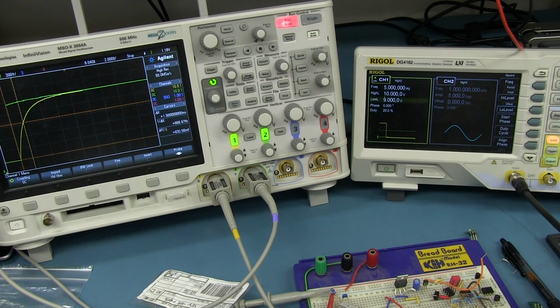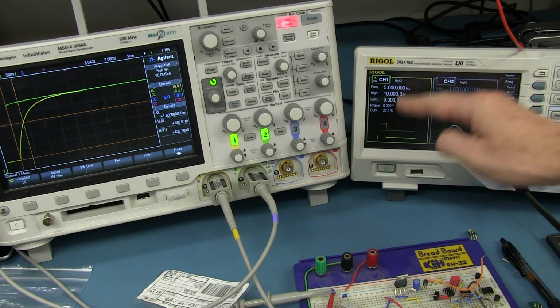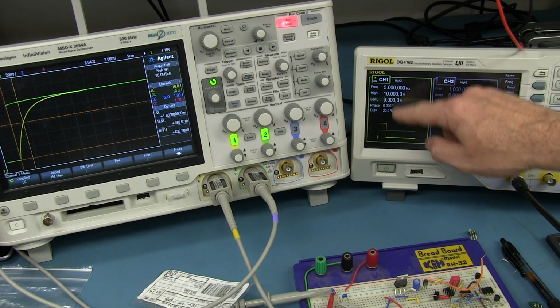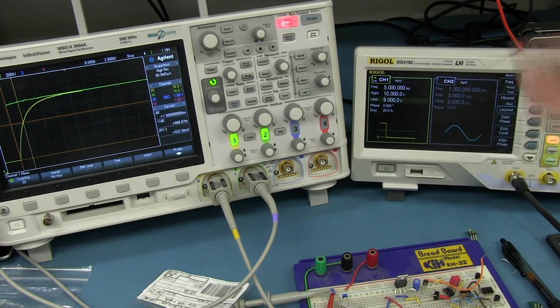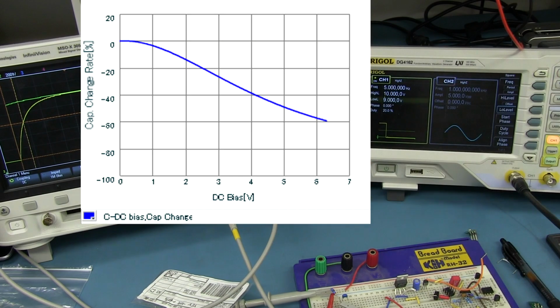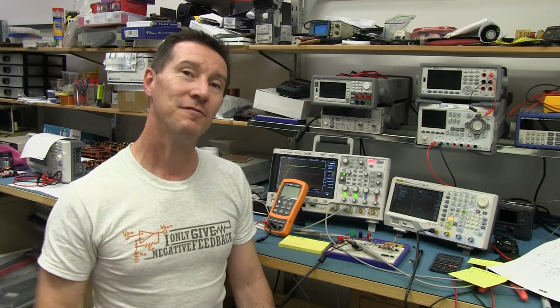I won't bore you with the details, I'll leave it up to you to experiment with this, but if you change that DC bias level, say 1 volt at a time, so if you went from 9 to 10, and then 8 to 9, and 7 to 8, and 6 to 7, and so forth, and dropped it down, or increased it, and then plotted that and measured your capacitance at each value, you would get that similar characteristic, a huge drop in capacitance versus your bias voltage, exactly like the manufacturers tell you, if you can find their data. So there you go, that's an interesting fact that not a lot of even experienced design